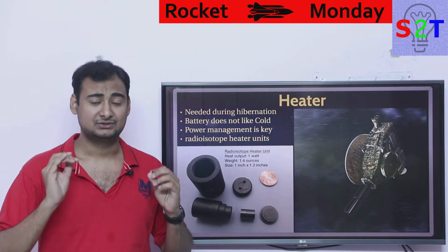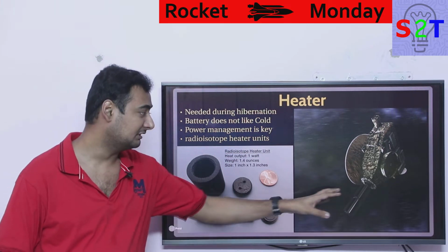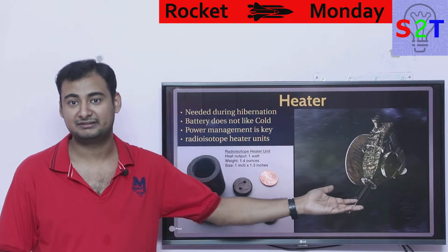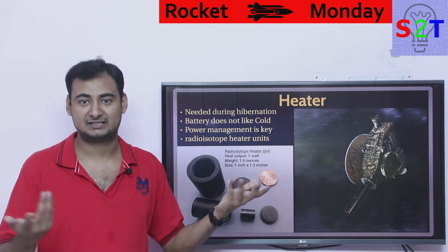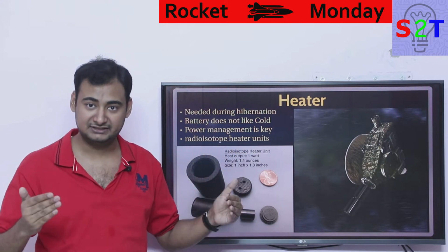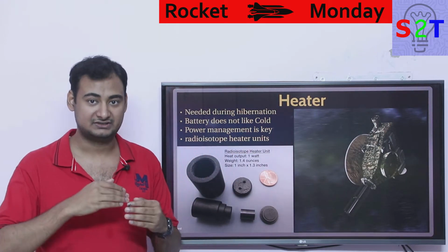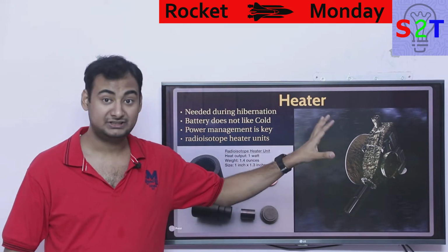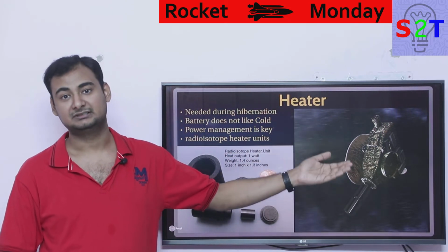So that inherently means whatever energy source you have, let's say this RTG, even though it's giving you 500 watts of energy, you're not using it. So it's just like disconnected. So that means this part will freeze. Even though it has insulation, no insulator is perfect, and it's not like the human body, which has like 100 watts of continuous power. So during that off period, the temperature goes down.